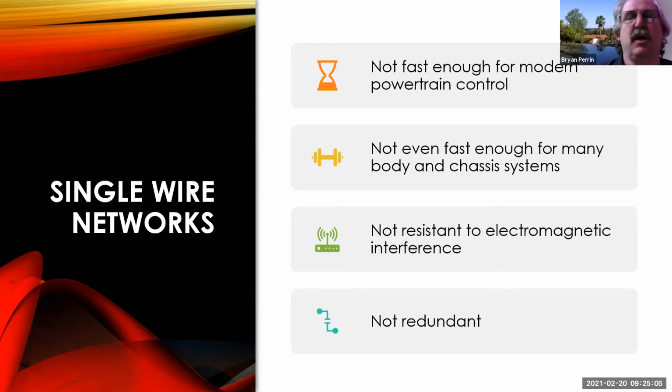I've sold a used body harness. Yeah, that's a good way. But I've gone in there and fixed networks with solderless connectors or solder. Usually what I do is, it's all about twists per inch if it's a twisted pair. So I count the twists per inch, and then I over twist to do the connection, so it kind of relaxes. And then you just have a small spot. If I can stagger the splice, I can. So instead of having...